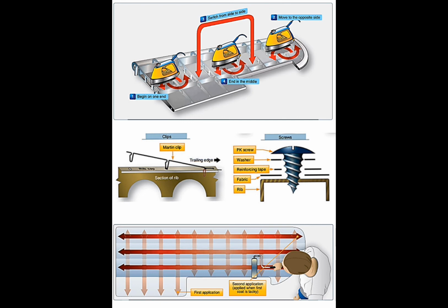Name the advantages of using the envelope method to cover fabric aircraft. Saves labor. All sewing is done by machine. It's like putting on a sock. Almost all stitching left to do is to the structure.